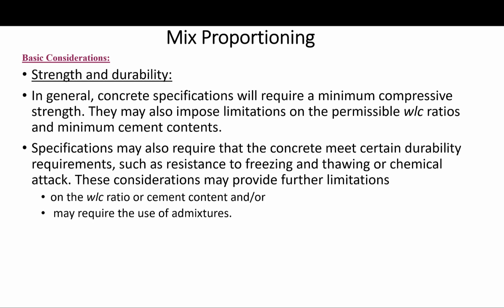It's not necessarily the 28-day strength that is most important. Strengths at other ages may control the design. For example, you need a certain strength at a certain age in order to strip the forms and reuse them. Or if you are casting post-tensioned concrete, where you have to pull the cables at a certain age, maybe 72 or 96 hours, you have to reach a certain strength. So the 28-day strength is not always the determining factor.